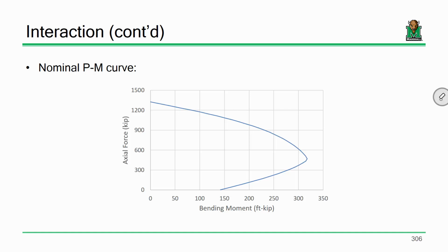How do you pre-stress a beam? I'm sure you all have heard of this concept before. The idea is you take an element of steel and subject it to a lot of tension. Now, if you're pre-tensioning, you subject it to tension, you cast concrete around it, you cut the cables. What happens to the beam? It locks in that compressive force. By locking in that compressive force, you take that beam and you make it stronger. By making that beam stronger, you can make it smaller. That's the concept of pre-stressed concrete. Now, there is a whole lot more that goes into it because there's losses and all sorts of stress checks that need to be done. But in the end, that's the general concept behind what is going on.